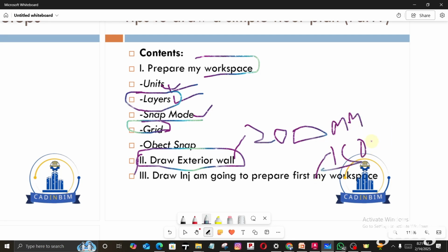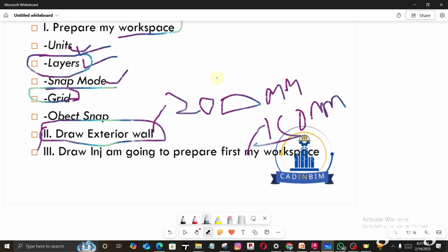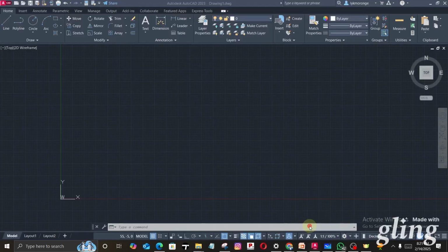So let's go back to AutoCAD so that you are able to draw the interior and exterior walls. Yes, we are together. Let's now go straight to AutoCAD. In AutoCAD, please be mindful of the size of the land for this floor plan, but let's just assume you take a polyline and draw the piece of land, just like a site plan. This is what I mean, like a site plan. You can simply come here, click on auto mode on, then click here.